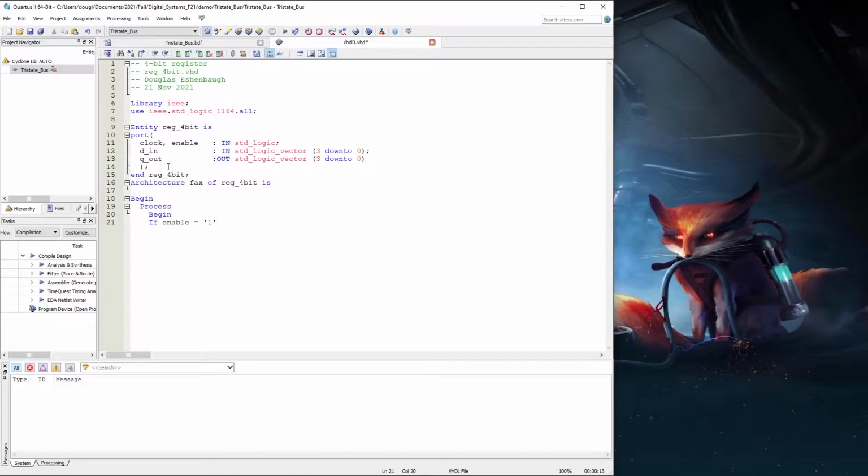Now, it might need to be a high, it might need to be a low. It just depends on the switching mechanism you're using. Remember, a lot of buttons go into the FPGA as a high naturally, so you'll want to have those as lows. And I'm using the rising edge function. You don't need to do this. If you feel more comfortable using the defining outer edge, that's fine.